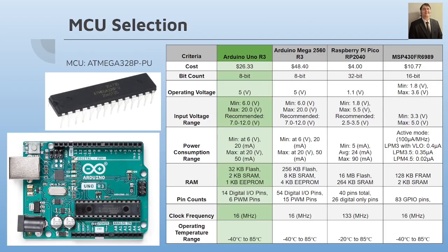When determining what microcontroller unit to use, we used the following factors to make our selection. The I2C peripherals would share the same 2 data pins, while the SPI peripheral would need 4 to 5 data pins. This means that very few data pins are actually needed for the project, so a lower pin count was sought. This project is far more hardware focused and only basic functions and calculations will be handled by the MCU.